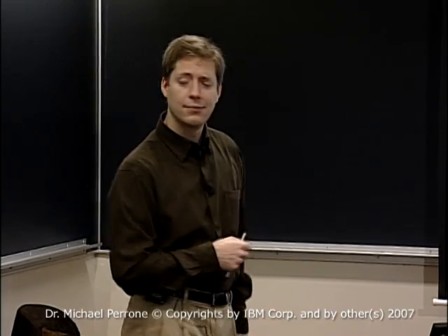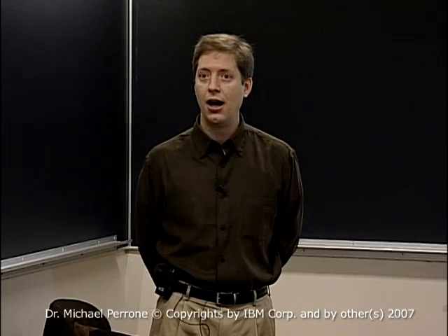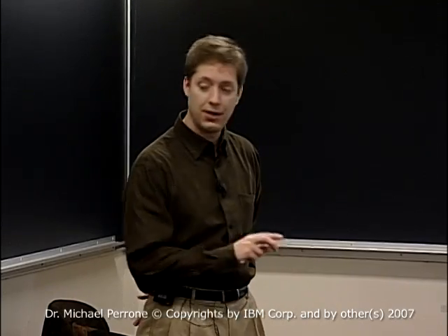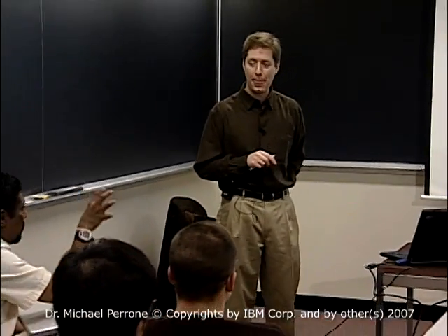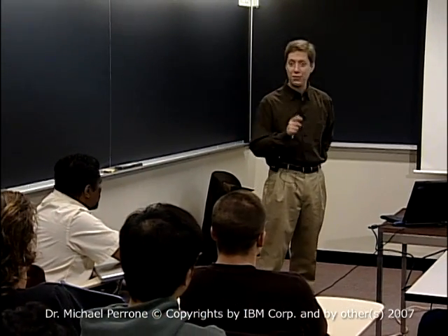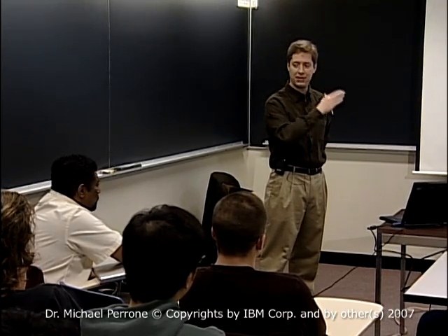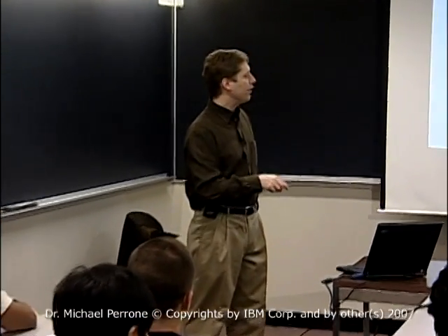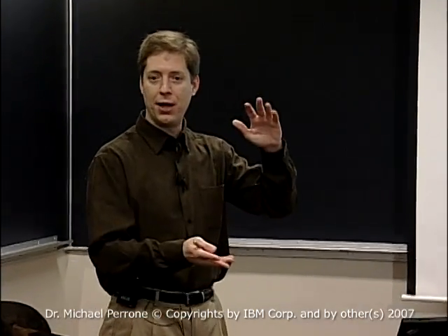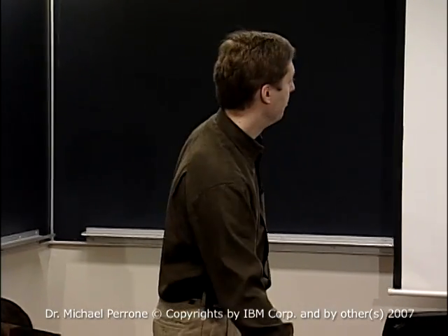So a DMA engine per SPU? Yes. It's not a global one? Right, that's correct. But there is a global address space. Yeah, but there's 16 slots in each SPU. Right, exactly. Each MFC has its own 16 slots, and they all address the same memory. They can have a transparent memory space, or they can have a partitioned memory space, depending on how you set it up. Each SPU doesn't have its own.